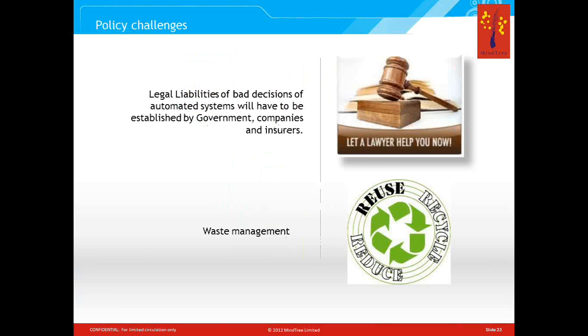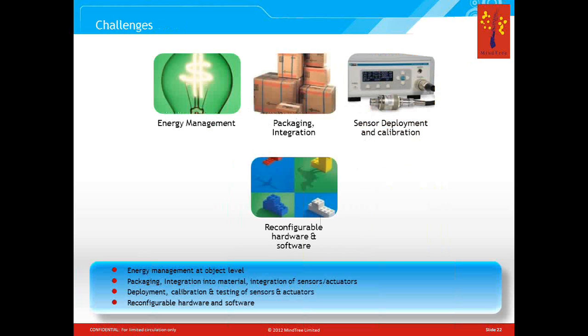Let me tell you one more thing. Another challenge which we can definitely see. We are talking about sensors and actuators. You know that sensors measure physical phenomena in real life. Now, the accuracy of these measurements depends upon how well they are calibrated. If it is well calibrated and up to date, then whatever it measures is going to be accurate, or at least you should know the offset. So, I'm off by so many degrees, so you take that into account when you take my measurement. You need to know that, otherwise you cannot trust it.